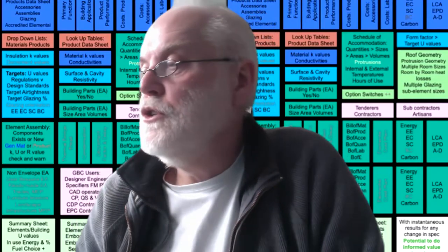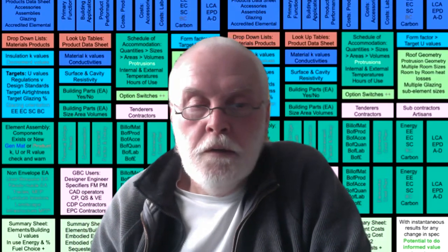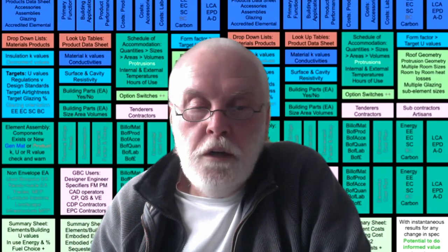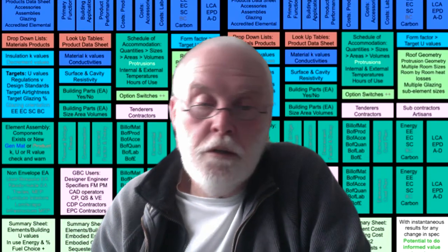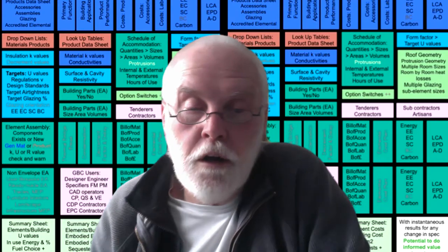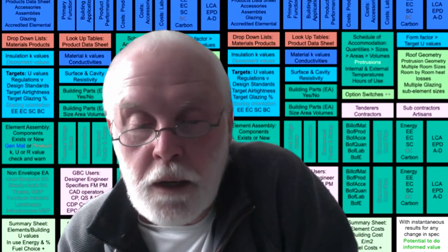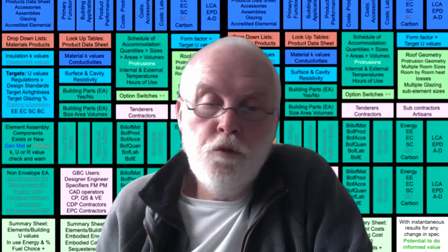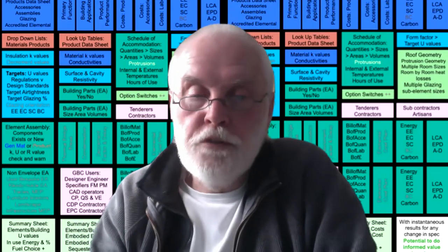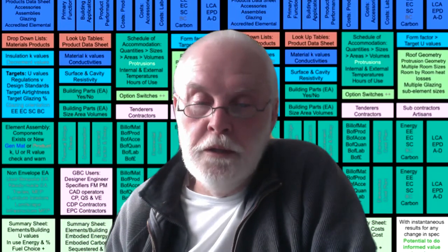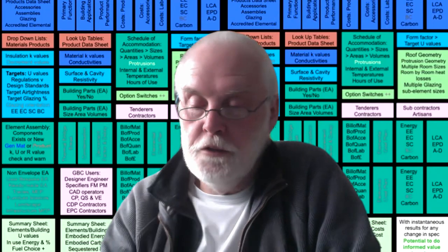And then we have the summary sheets where we've got elemental building U values, in-use energy, and percentages for different elements, so that we can see that windows perform very badly, even though they're very high performance, and we can then reconsider whether we need to spend more money on the windows. Fuel choice plus fuel carbon factors equals in-use carbon. The summary sheets for the elements of the building: embodied energy, embodied carbon, sequestered carbon, biogenic carbon, life cycle assessment.